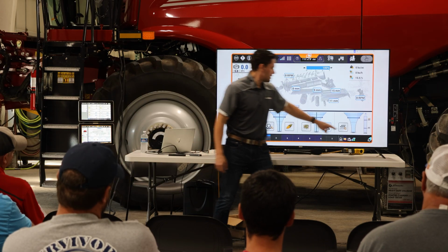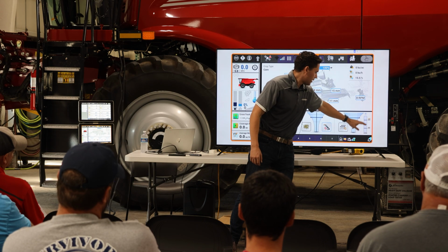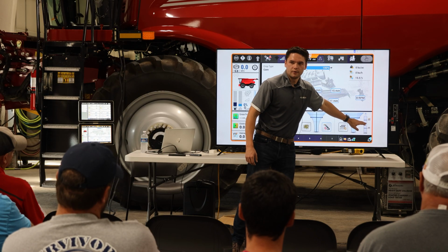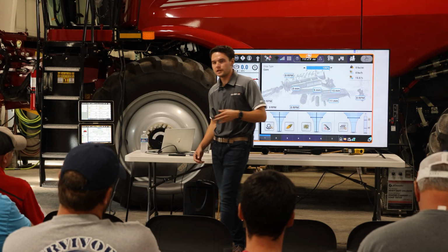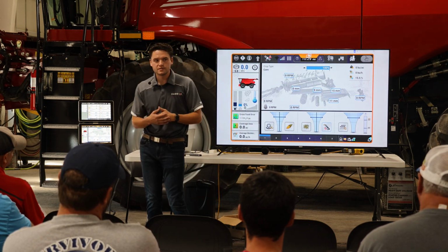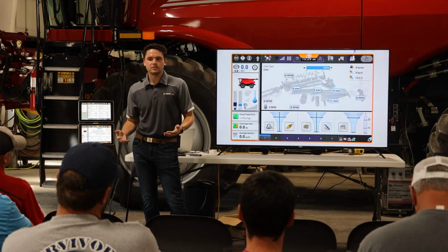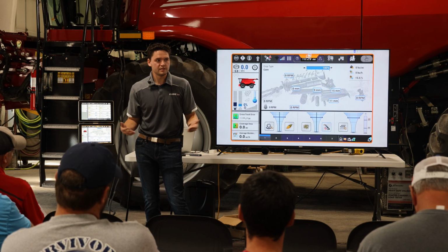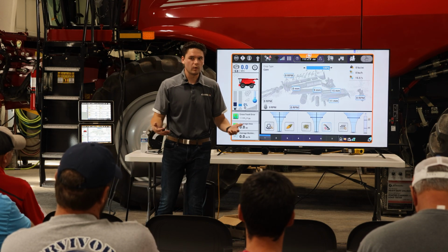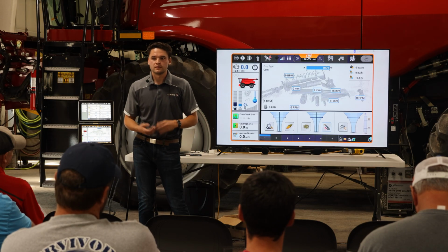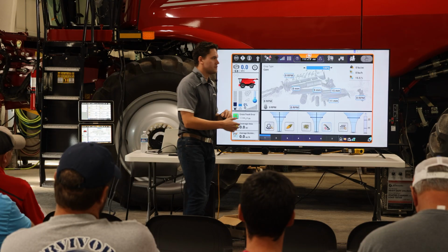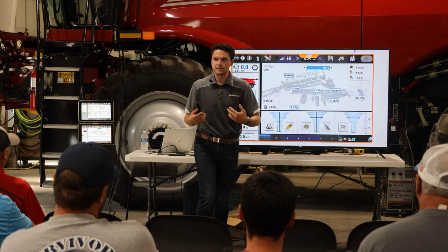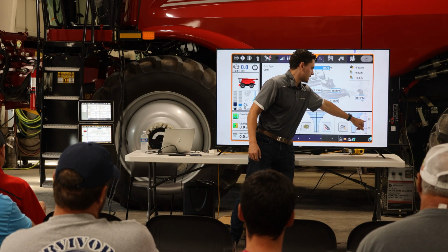So in normal operation, ideally, you are above this mark and below this mark. Preferably what I like to see is as close as we can to the top without overloading it and creating sieve loss, because why would I not put as much load on my sieve as I can? Because if I am underloading my sieve, I'm leaving what on the table? Capacity. Exactly, capacity. So we want to load the sieve as much as we can while having the least amount of losses. And this will be a good indicator.